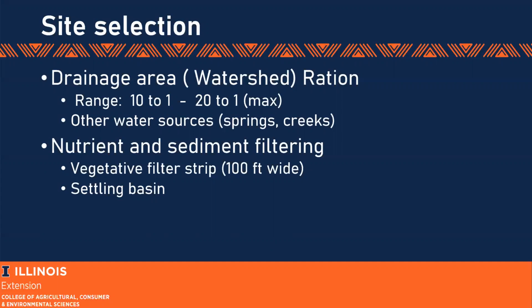Is there a strip in there where we can run what we call a vegetative filter? Run the flow through a grass and plant area that's fairly dense and fairly level right to left, if you're looking up or down it, and not a real steep slope. So it'll take us time to run through that area, and that vegetative filter will pull out a lot of the sediment. We'll let the sediment settle out, and the vegetation will pull a lot of the nutrients out of the water.